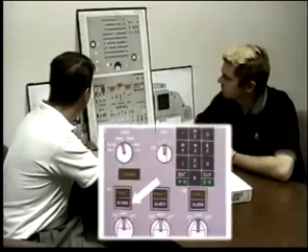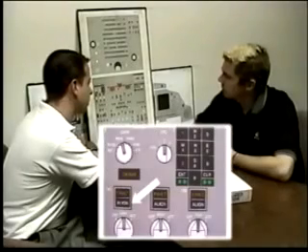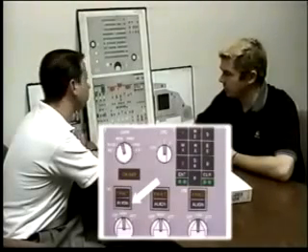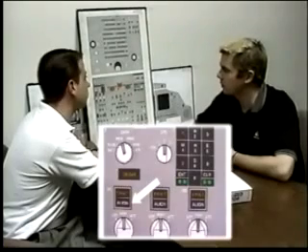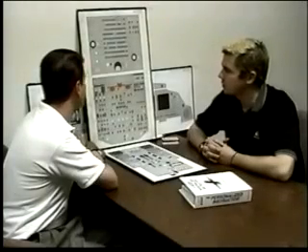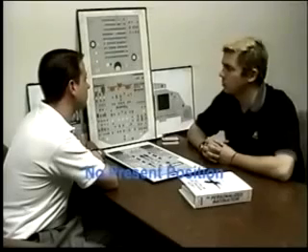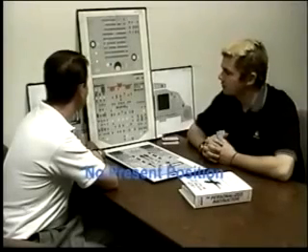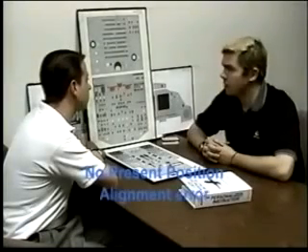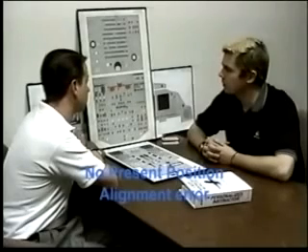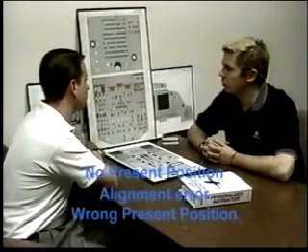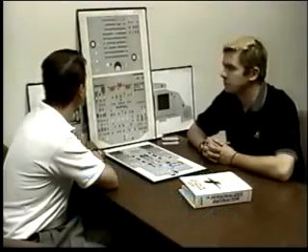Three conditions for a flashing fault light. What are those conditions? Well, the one we typically see is during the pre-flight, we've come in and we've turned on the ADIRs, but we haven't entered a present position within 10 minutes. The other reasons are an alignment error, or if I've entered a position that is more than 1 degree latitude or 1 degree longitude off of the last known position.